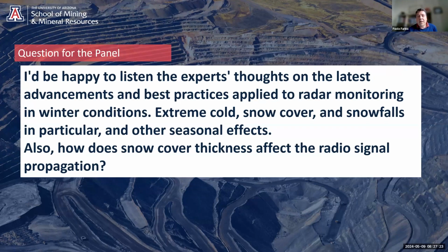And of course, in general, we have to be careful when there is snow accumulation or snow melting. You have to pay more attention in interpreting the data, and sometimes you cannot get the same level of reliability. You need some kind of manual interpretation, or to filter out what could be a real alarm from a fake alarm. So that's something that probably involves more effort from the user's point of view, in my experience.